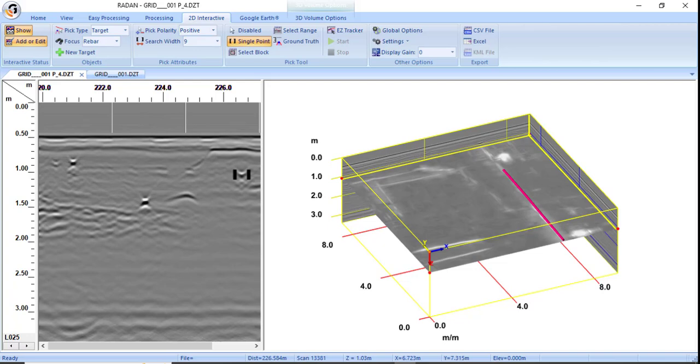Because the hyperbolas occur at different depths on the GPR profile, you can choose, let's say, 2 or 3 velocities and tell the program to average these velocities and make the best migration for your GPR data. Now I will continue adding interpretation